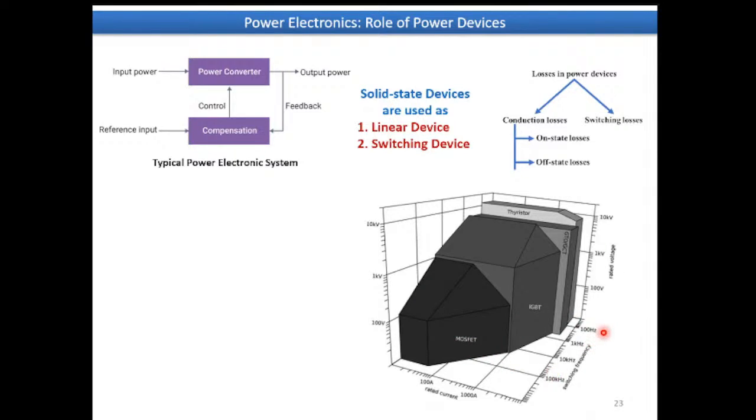With the years, in case of power devices, we intend to operate our devices at very high frequency. These are power devices, high voltage, high current, fine. But why do we need to operate our devices at high frequency? Because this is a power converter, and along with the power device there are a lot of other associated components like different inductors and capacitors. If we operate our overall power electronic circuit at very high frequency, all the other associated component sizes will reduce. Remember, the size will reduce, so our overall power electronic system will be more compact.